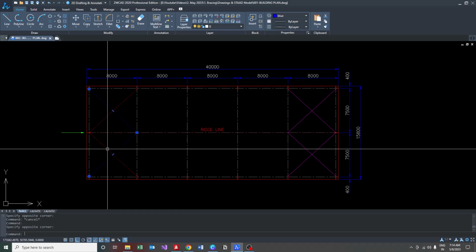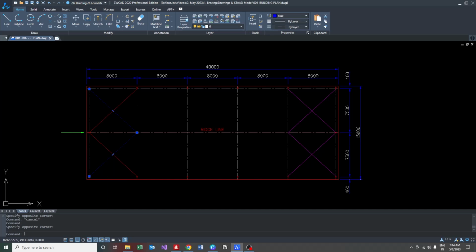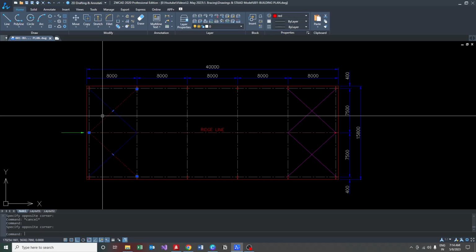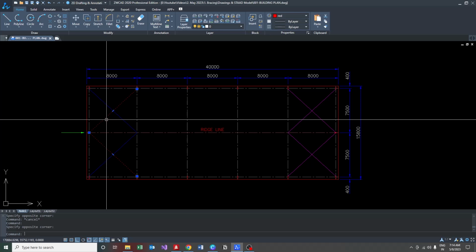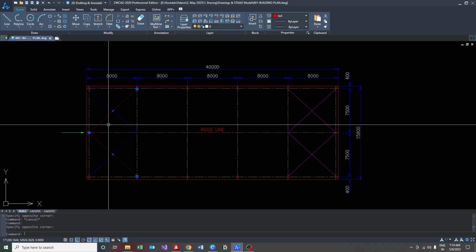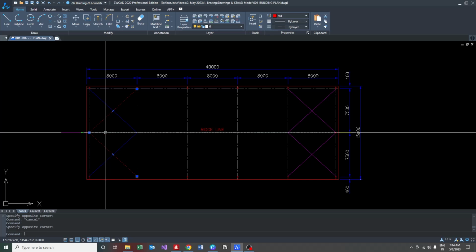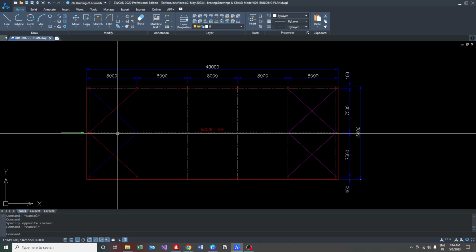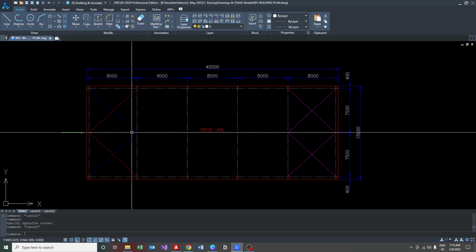Why is it so? The reason is, say the wind load is pushing the rafter. This pair of rods would be subjected to compressive force. What happens if you try to push a very slender member? It will buckle away, right? The same thing happens here as well. These 2 rods would buckle away and the force flows along this line to the next rafter.